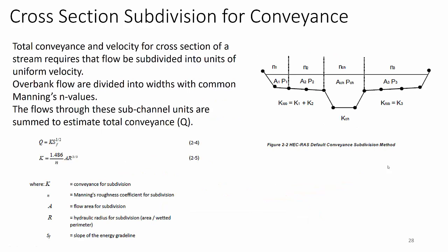And the flow control systems are the cross sections. So we manage the cross sections so we understand the cross sections and resistance to flow. And what we do by managing these cross sections is we spread them out, we constrain them, we build them up, we put things in the middle of them. So all a weir is, is taking a large cross section and making a smaller cross section out of it.